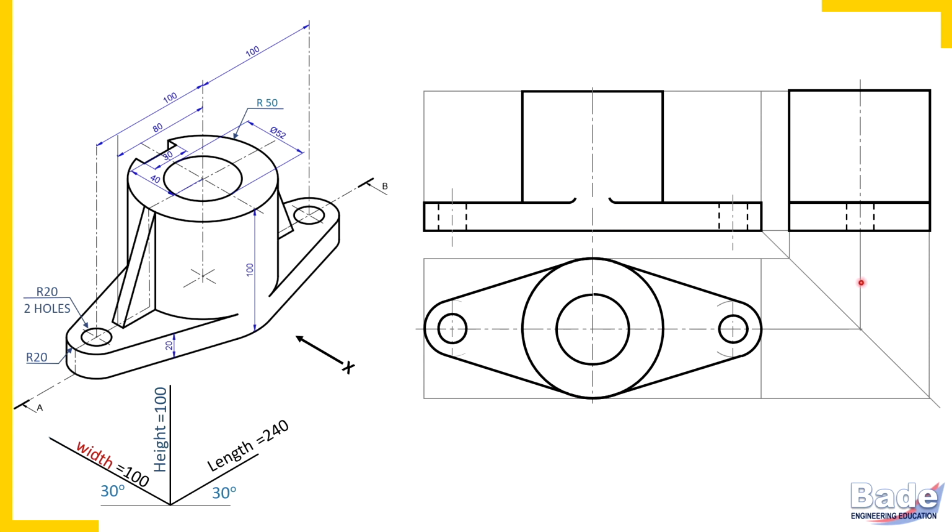Now in the side view also, where it is tangential to the curved surface of the cylinder, from that point you should draw a projector. Check now, focus on this portion. The way we erased this edge, this dark line here, similarly here also I have erased that dark line. Check and show the curved joint in this manner. So from the left side view, this joint is visible here.